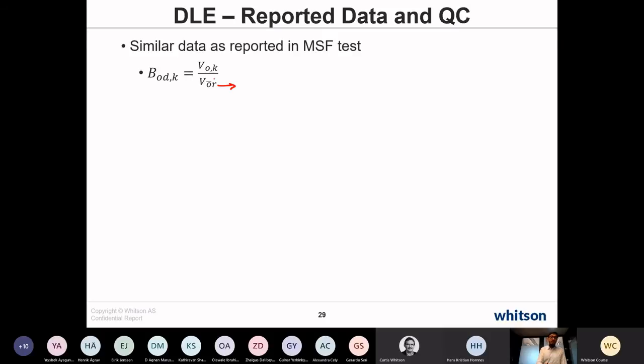So you are using the residual oil volume as a reference. Yes, Curtis. Even if you're predicting exactly the correct oil shrinkage from bubble point to the first pressure, and if you're getting an exact prediction of the correct oil volume shrinkage during the test, you'll calculate the wrong BODs. So even for a perfect match, you'll get seemingly wrong data. Yeah, that's correct, and we will see an example of how bad it can be if you don't include the shrinkage, for example.